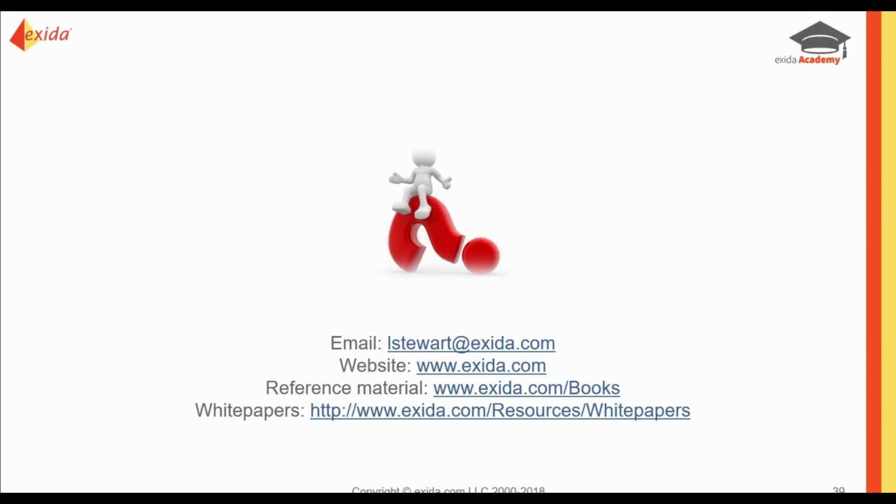We have a question about redundancy. If SIL2 is only achievable with redundancy, that's not necessarily always the case. You're going to have to do a detailed look at the SIF verification, kind of like we did in the Excelencia examples, to see exactly where you fall with redundancy. If you were meaning my example specifically, no, you can achieve SIL2, especially SIL1, without redundancy if you have the right devices in the right application.